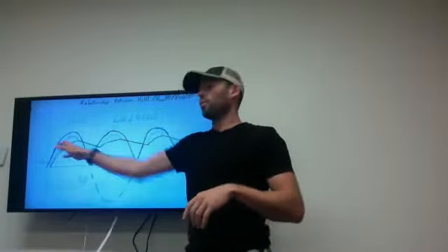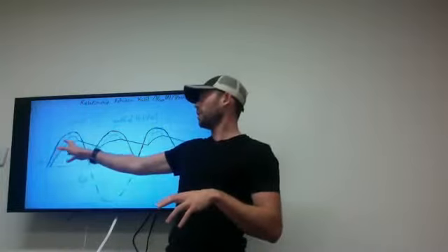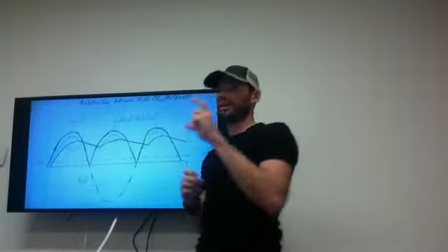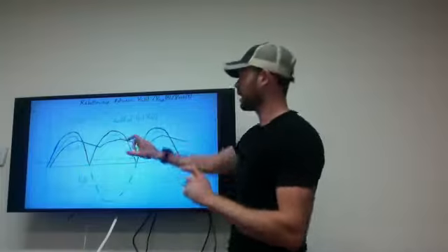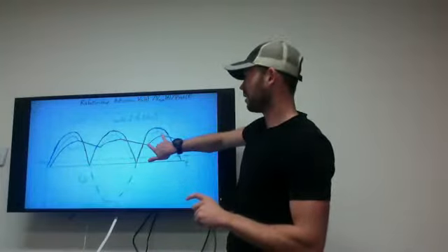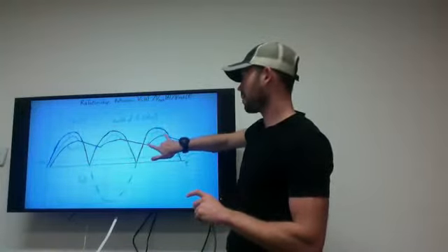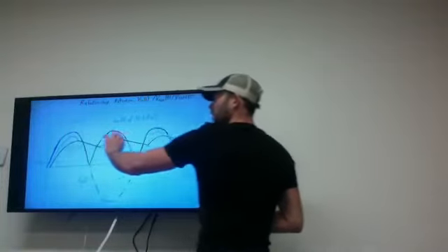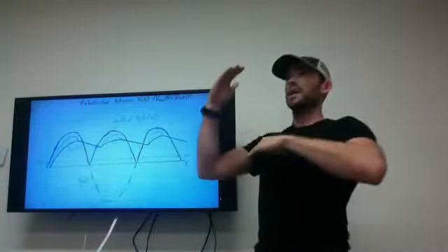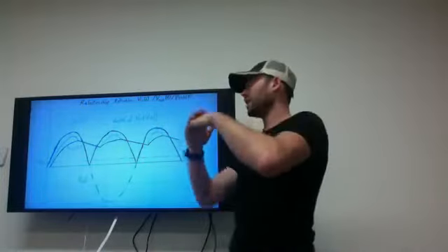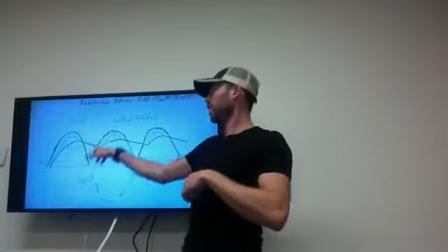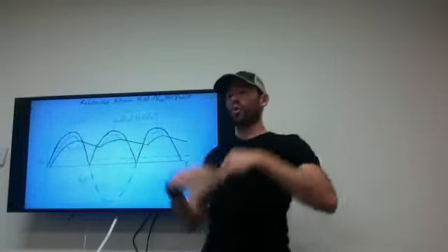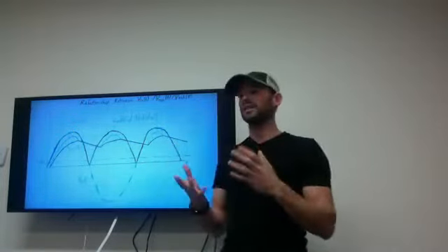To find the actual DC voltage, we take the average between the trough and the peak of V out all the way through. That is how it's smoothed out. If we didn't do that, every cycle of the rectified signal would basically turn off your devices, which would be almost useless.